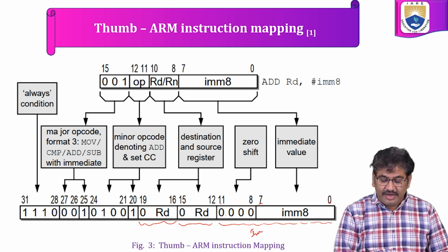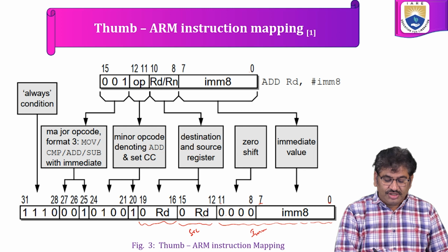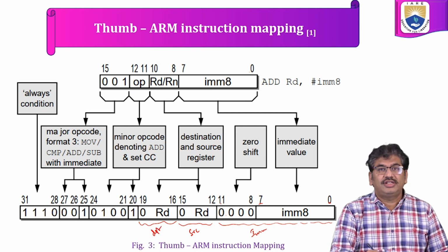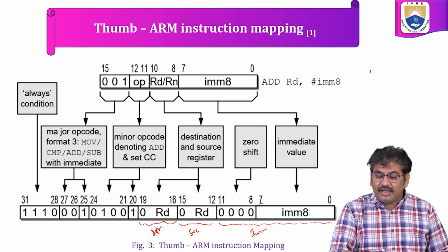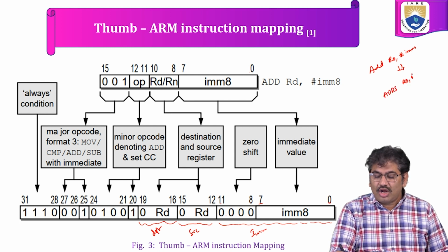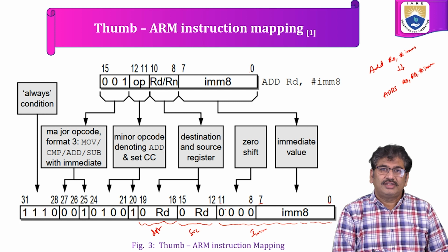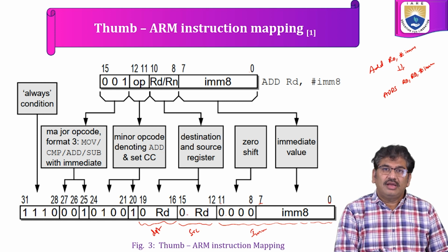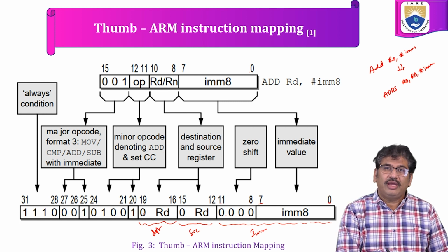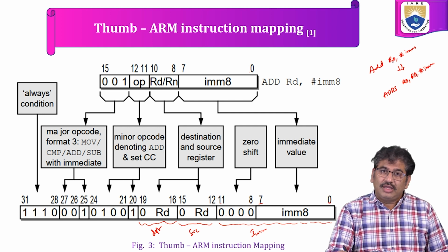This is immediate data, this is the source register and this one is the destination register. As we have seen in the earlier case, ADD R0, #immediate data will be converted into ADDS R0, R0, #immediate. So the immediate data is placed from bit 0 to bit 12, that is a 12-bit offset, followed by the RD register, which will map the 2 address space into 3 address space.